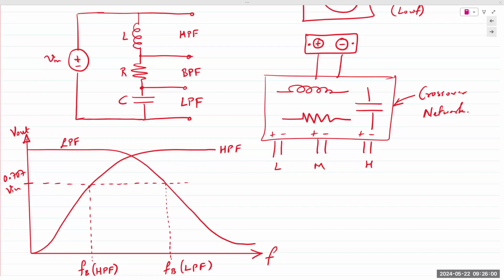We can just do a frequency response. Yes. You can do it with an oscilloscope if you just want to use that. So the question being asked is, how can we test the performance? The performance of a filter can be tested in a variety of ways. Oscilloscope, of course, is an option. And if students are taking the lab this week, the resonant circuits lab, lab 7, you will test the performance of a resonant circuit, and you'd obtain a chart that looks like this. So it looks like a bell curve.